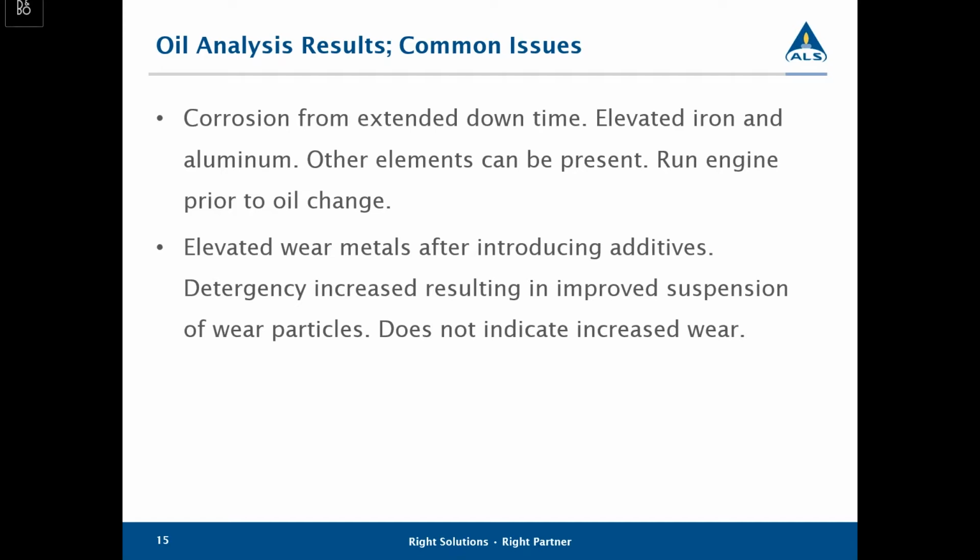So they have very positive effects, and they can help clean out where maybe there's particles that have settled. But what occurs is if you haven't used that additive before and then you start using it, you'll see an increase in wear levels because there's more wear particles in the oil. It doesn't mean that there's something bad occurring, and it doesn't indicate increased wear in the engine. You're just getting increased particles suspended in the oil.